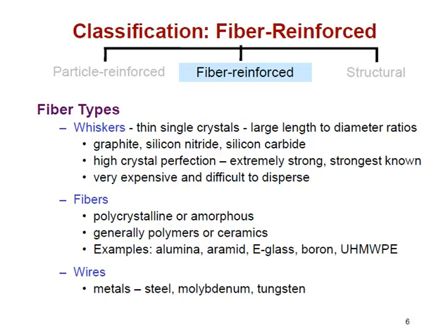They're not practical to use in huge volumes just because of their high processing cost and difficulty in handling. More often it is a fiber which is used as fiber reinforcement, not surprisingly because of the name. And these can be manufactured in mass, in bulk, much more easily. These are polycrystalline. They can either be crystalline or amorphous, typically crystalline, and in the case of polymers, they'll be chain aligned, such that those covalent bonds are all aligned in the axis of the fiber, and that's really what gives them their strength.